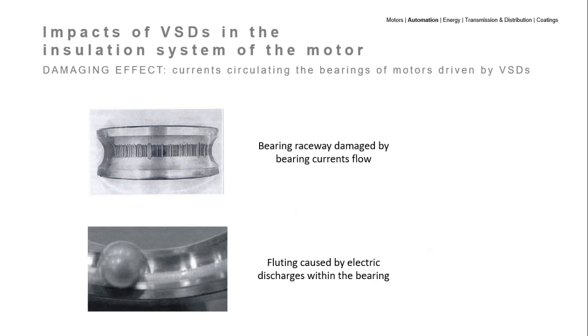Equivalent circuit of the motor for the high-frequency capacitive currents are shown here. Here, a little bit more detail of the common mode current impact on the bearings. The rotor is supported by bearings, which have a film of non-conductive grease. At high speeds, there is no contact between the rotor and the outer race of the bearing, which is grounded, due to the flat distribution of the grease film. The rotor potential can then rise relative to ground to a level capable of breaking the grease film. Sparking occurs and discharge current flows through the bearings. This current circulates when the grease film is momentarily broken and it's called capacitive discharge component.